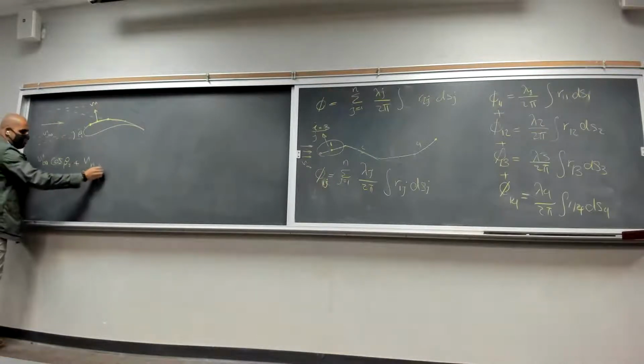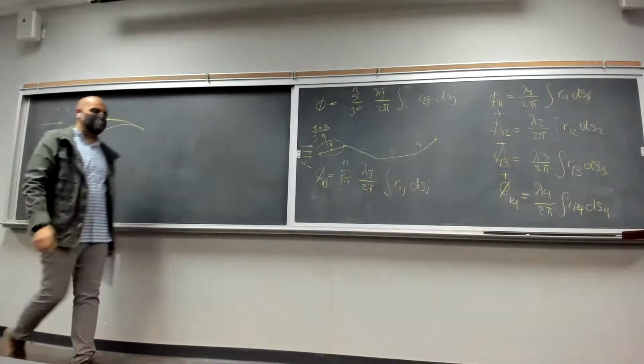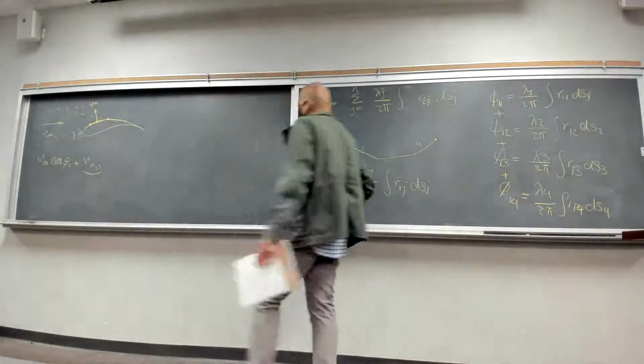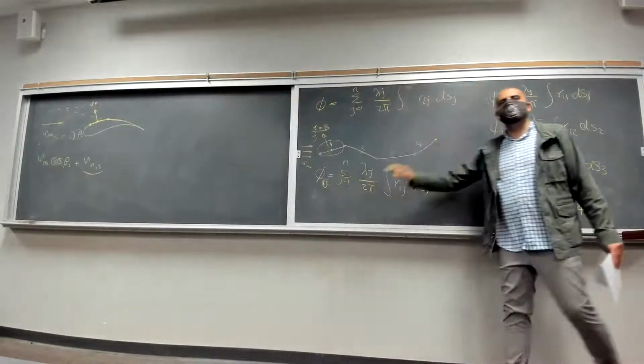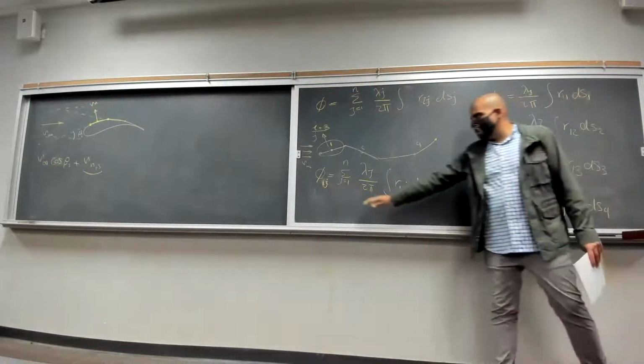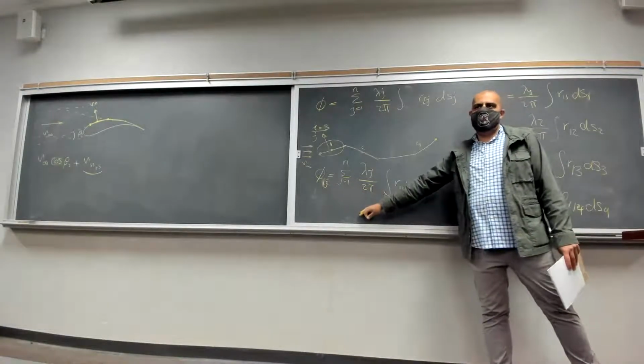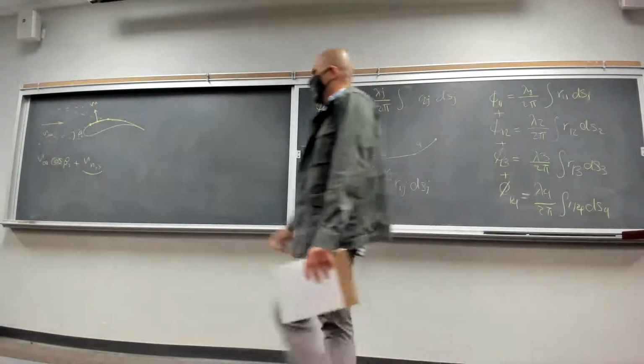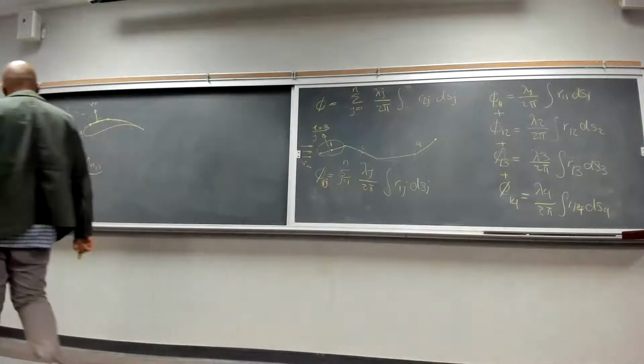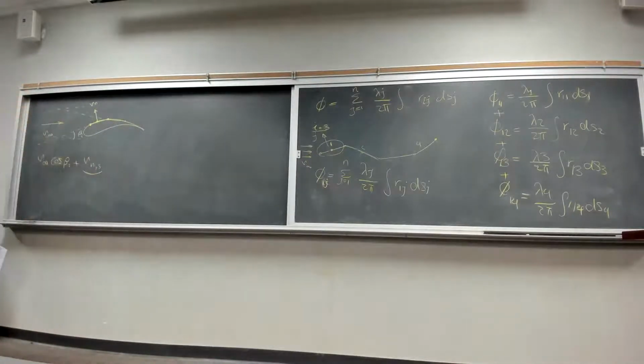What is this velocity? How can we calculate this velocity using the velocity potential for each panel? We have the velocity potential for one panel here, panel I. How can we calculate the normal component of velocity in that direction? Exactly.